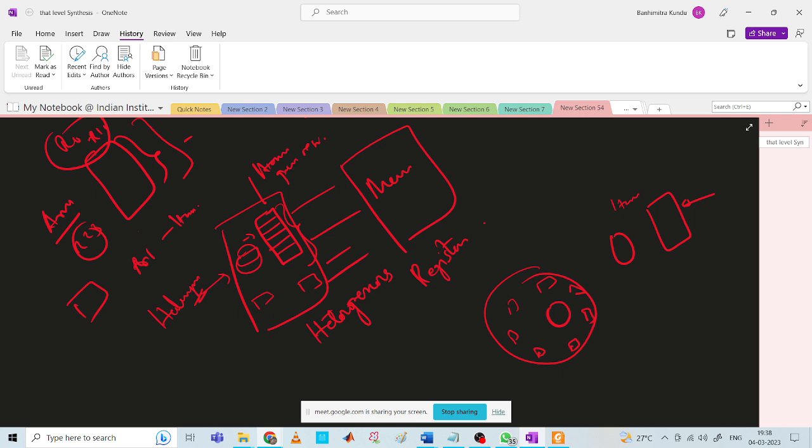Anything else? If you want to study the ARM processor registers, there is a set of registers R0 to R15, I guess. So this is in a single register file. This is called a homogeneous register set. But there are some other registers, like the link register and the main stack pointer register. So these are all part of the heterogeneous register set.